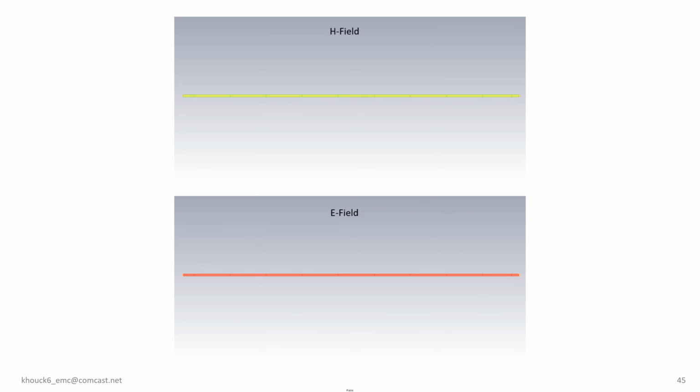As this reflection reaches the source, the voltage and electric field are compelled to match the source voltage, causing a proportional decrease in current. The weakened electric field and magnetic field then propagate towards the termination once again. Upon reaching the termination, the decrease in the electric field induces a drop in voltage across the resistor and an increase in current through the resistor.